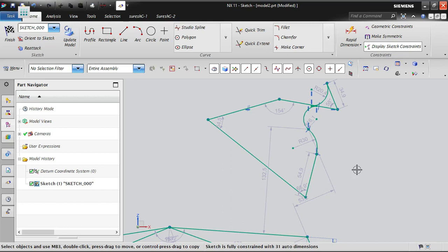This auto dimension helps the designer to quickly constrain the object, but at the same time, a lot of unnecessary dimensions will get created, and it won't be in line with your design requirement. We are always working for the design that we have now or are supposed to create. Unnecessarily all these dimensions will create an unnecessary design intent, so that it will cause a major rework for our model as well as the sketches. So don't use this continuous auto dimensions.